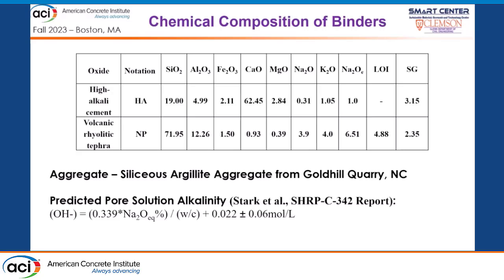But again, to the point that was made earlier, the available alkalis or the alkali release from this plays a big role in how these materials perform, and you'll see that. One of the things we've done in this study is to match the soak solution composition with the pore solution composition for all of these mixed variables.